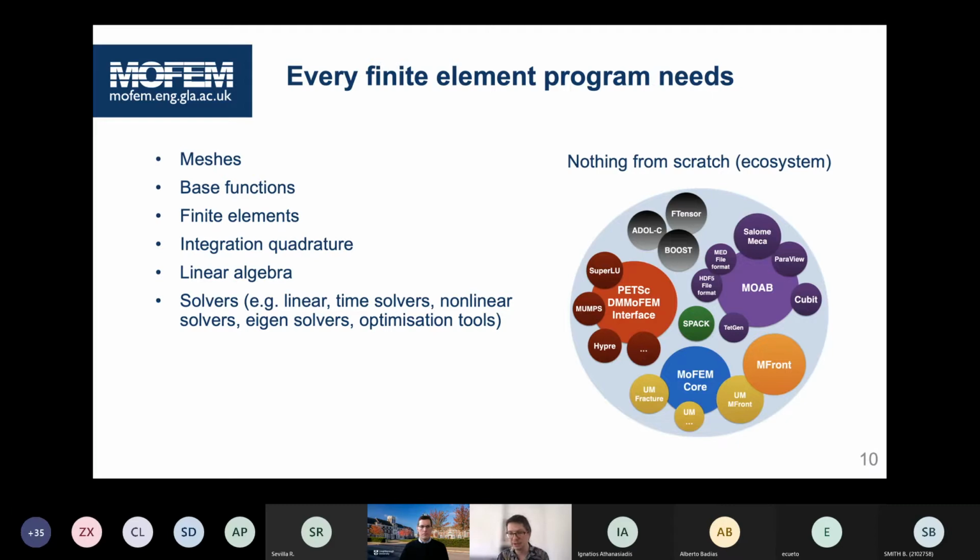And this software ecosystem is based on three legs for stability. The first thing is MOAB, which is a library which manages the topology, and through that library we can read various formats, and then you can do very complex operations on the mesh and manage data on the mesh itself, block sets, side sets to manage boundary conditions.